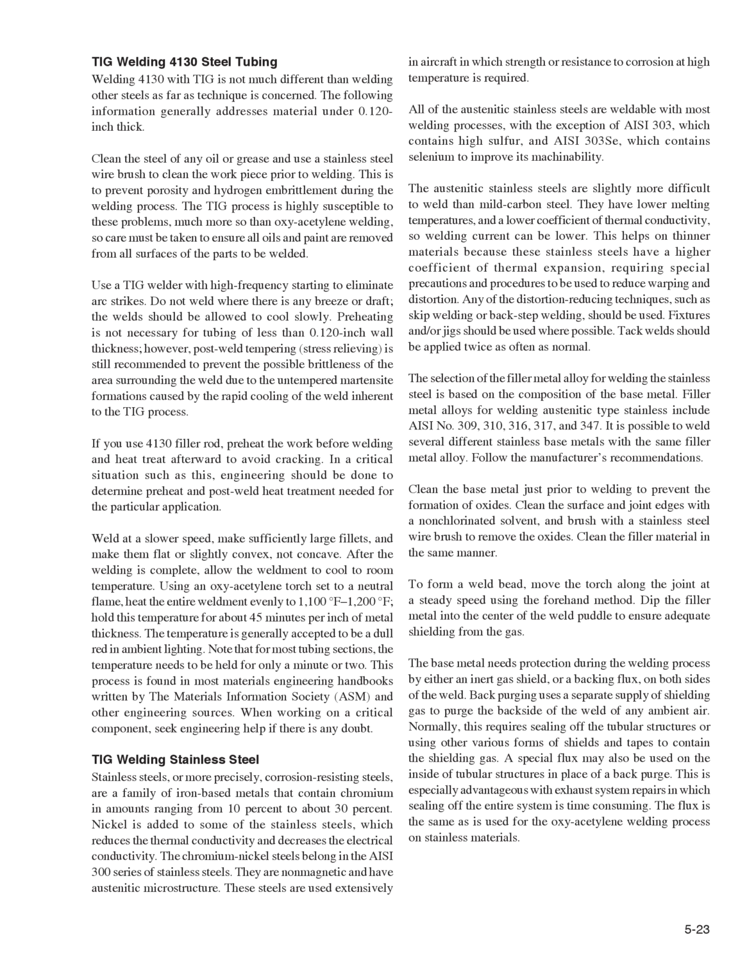If you use 4130 filler rod, preheat the work before welding and heat treat afterward to avoid cracking. In a critical situation such as this, engineering should be done to determine the preheat and post-weld heat treatment needed for the particular application. Weld at a slower speed. Make sufficiently large fillets, and make them flat or slightly convex, not concave. After the welding is complete, allow the weldment to cool to room temperature.